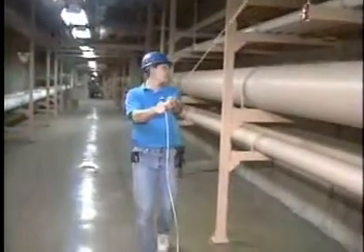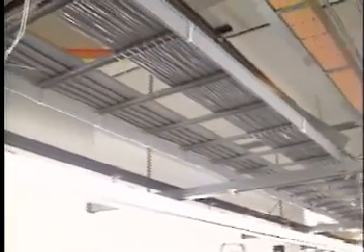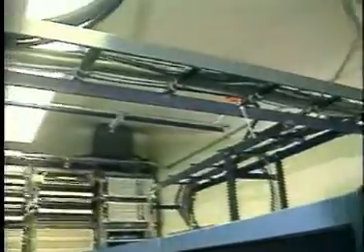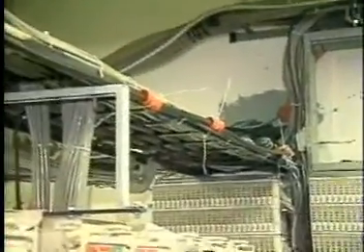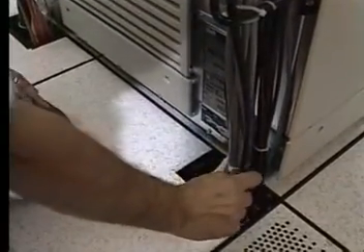For short-distance installations, mechanical pulling equipment and lubrication are usually not required. When pulling cable by hand, remember to apply even tension rather than a series of sharp tugs on the cable. For cable installed in exposed cable trays or raceways, it may simply be laid in place or pulled through ducts installed in the raceway. As with all installations, bend radius is a critical factor. Cable clamps or tie wraps can be used to prevent cable movement, especially at corners. However, the cable must not be crimped or squeezed too tightly and must be protected from sharp edges.